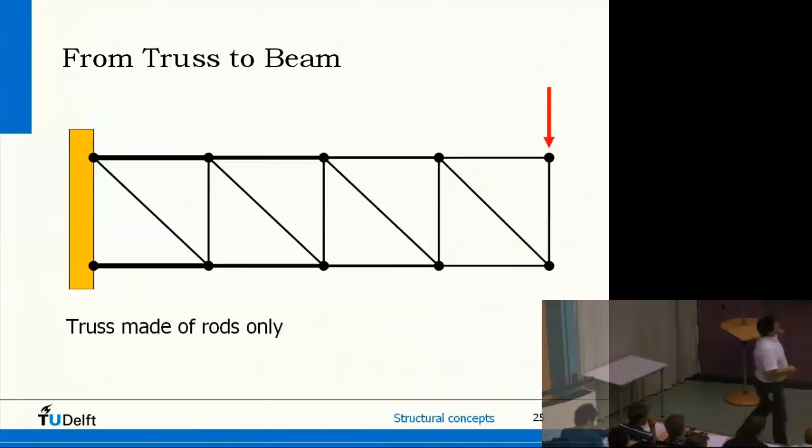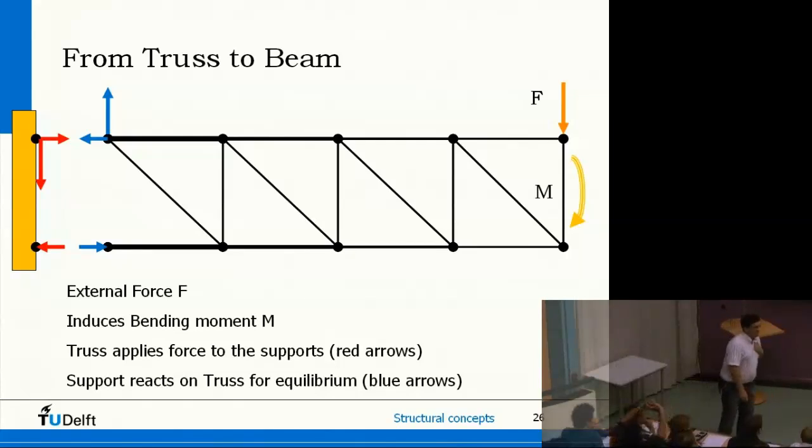No, maybe not. Well, here you have actually more or less the same system, but now you use diagonal bars, and here it is split into forces and bending moments. So if this is my beam, this is my object, what I'm looking for, there's one external force, and that's this force. What I need now is reaction forces on that end that result in my beam maintaining its position.